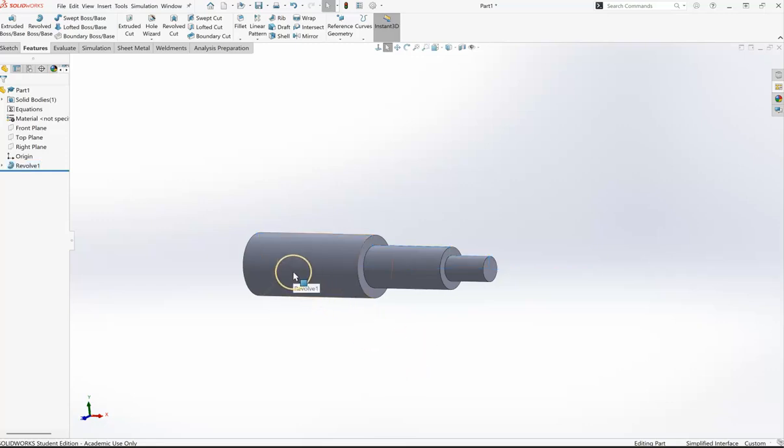Again, we could have done the layered cake approach. We could have drawn a circle and extruded it this way, started a sketch here, drawn another circle and extruded it this way, and then done the same for the third. This is just a different way to accomplish this. So that was a very simple revolve. We're going to end this sketch here now, and with the next video we will start with the class lecture in the book that begins on page 207.